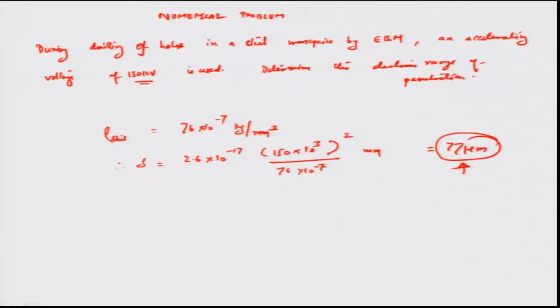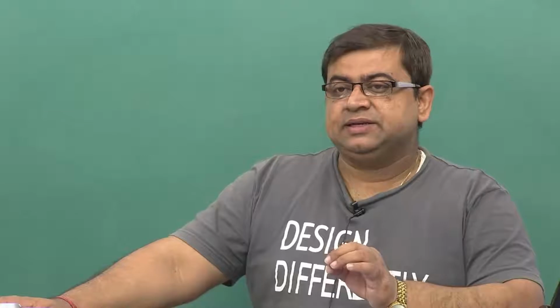So, you can already think of the extent up to which an e-beam can penetrate. It is about 100 microns, which is close to the diameter of a human hair. So, this much is the kind of penetration depth that would happen if the e-beam were to strike on a surface. Obviously, as the process is happening continuously as a function of time, the drilling could become a through hole as more and more heat is added and more layers are disturbed within the surface.